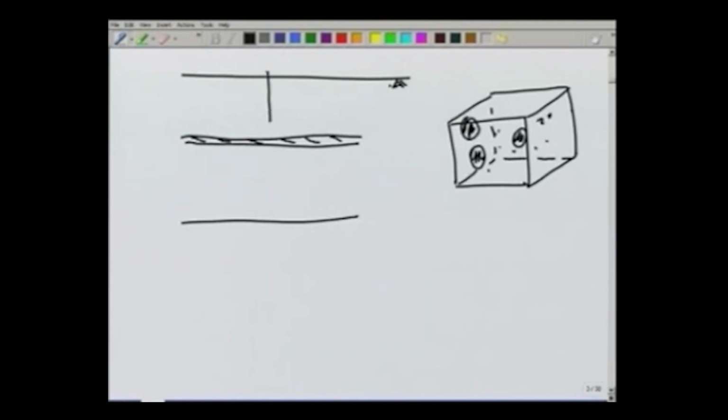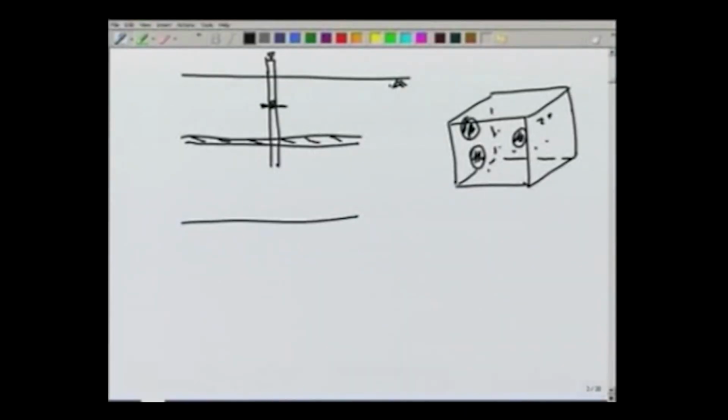If we put a tube here, a piezometer here, water will rise up to a certain level, which may be below the ground level, it may even be above the ground level, in which case it is called a flowing aquifer. Now, suppose the piezometric head is here.